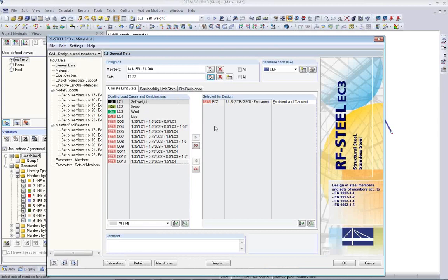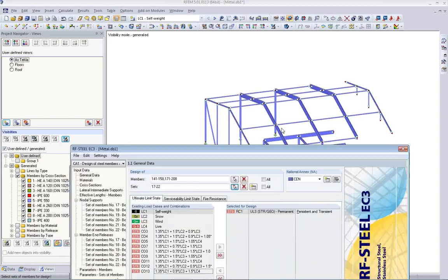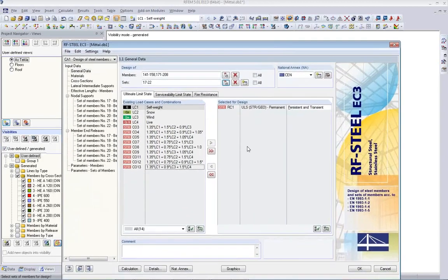The design length of these main girders is the entire length from the wall to the pitch of the roof, and it has a local support which is held by the frame, which I forgot to enter, I see, which is supported by the bracing, which I forgot to enter, in the center. So the buckling length in the weak direction of the cross section is smaller.